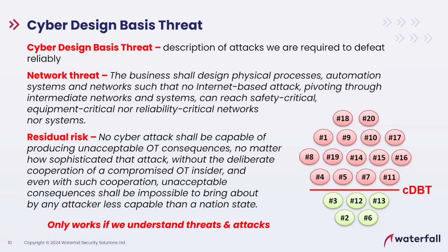We need to translate that into a security level. That's what 62443-3-2 says. That's the minimum we have to do. What I suggest, what cyber-informed engineering suggests, is that, because cyber threats are deterministic, not random, the right way to model risk is as something called design basis threat.